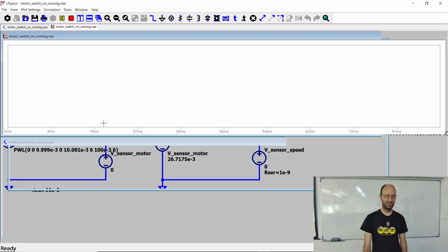So remember, this is what would not really work in our model that we have built. Just with the viscous friction, you would just get a linear curve. If we add constant friction, like this way, we turn the motor in the opposite direction. So this does the thing that the motor would not turn in the opposite direction.